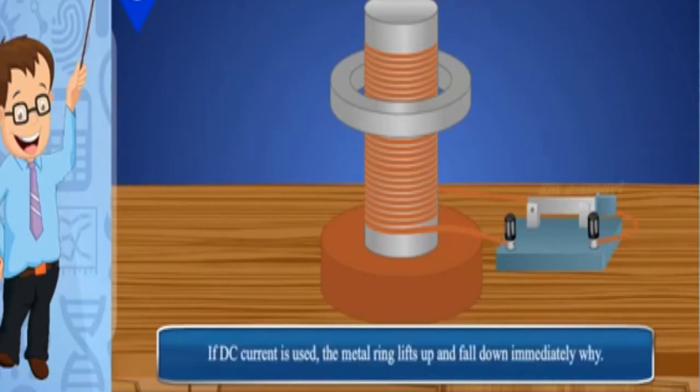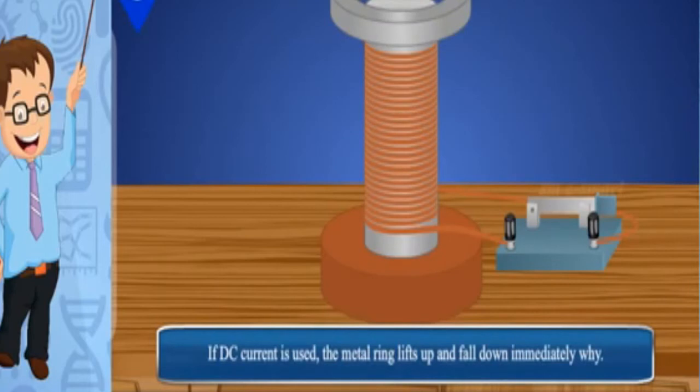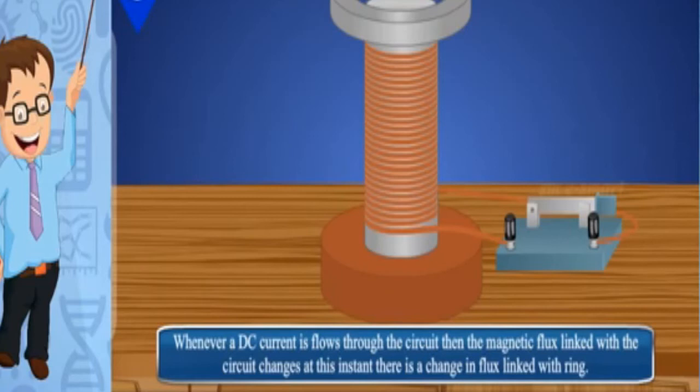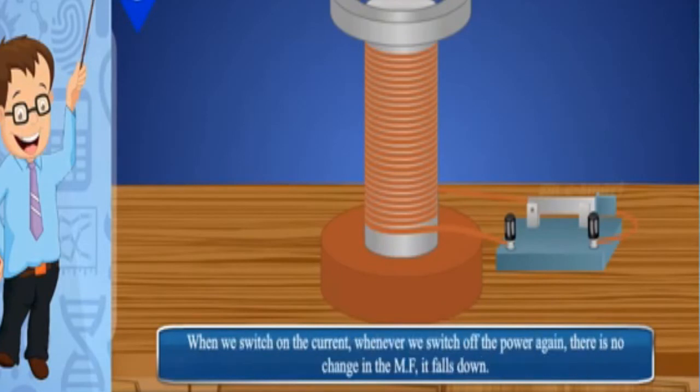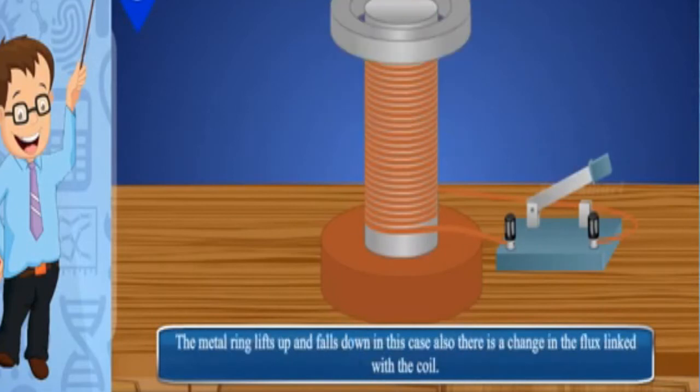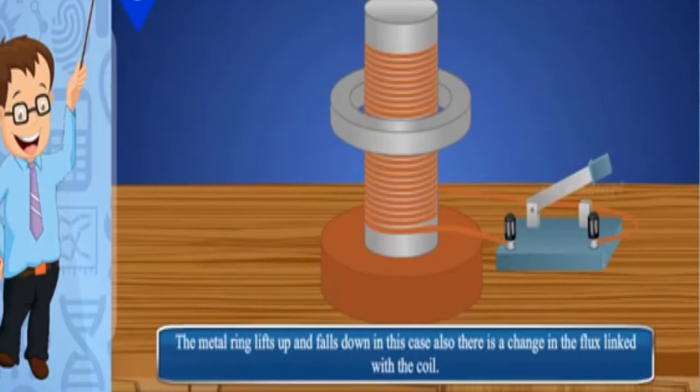If DC current is used, the metal ring lifts up and comes down immediately. Why? When there is no current passing through the coil, the flux linked with the ring is zero, and there is no change in the position of the metal ring. Whenever a DC current flows through the circuit, the magnetic flux linked with the ring changes at that instant. There is a change in flux linked with the ring when we switch on the current. Whenever we switch off the power again, there is a change in the magnetic flux. It falls down. The metal ring lifts up and falls down. In this case also, there is a change in the flux linked with the coil.